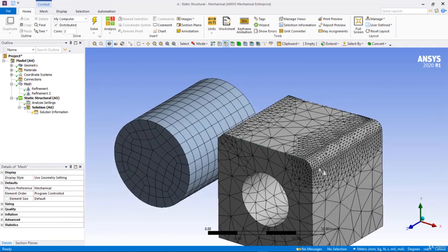So you can directly use the surface refinement at different blends or fillets and other things. Where you have straight edges like chamfers, drafts and other things, you can go for the edge refinement options.